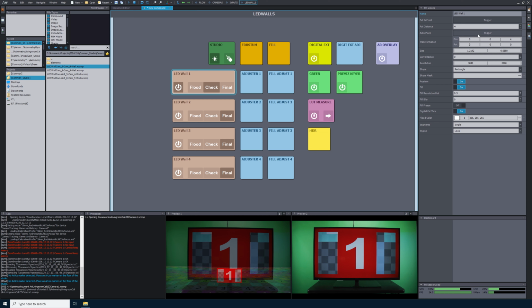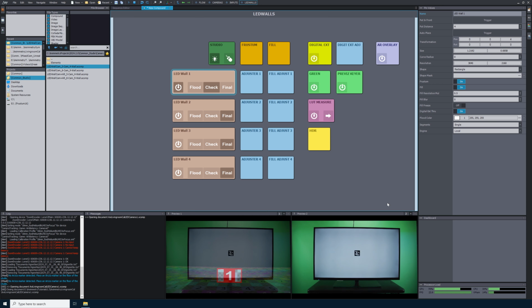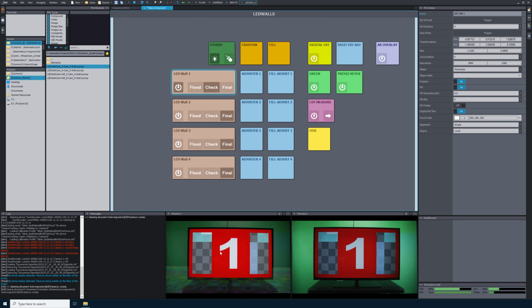Next, we will use this auto place trigger. This will display an ArUco marker on our screen, and then it will place the virtual screen over our physical screen. So I will just select this auto place trigger. We'll see the ArUco marker, and then we will see that the overlay matches both on our physical volume and in our virtual world. This placement should be very specific for your volume. So if your resolution and size are correct, you shouldn't see any ghosting. I can now make some slight adjustments to my transformation. I just want this overlay to be perfect so that the white and black checkerboard patterns line up perfectly with no ghosting between the two images. As I continue to adjust these transformation settings, you will see the ghosting that I am talking about.